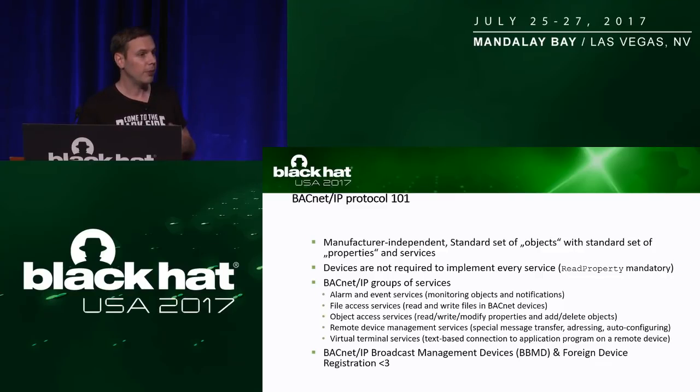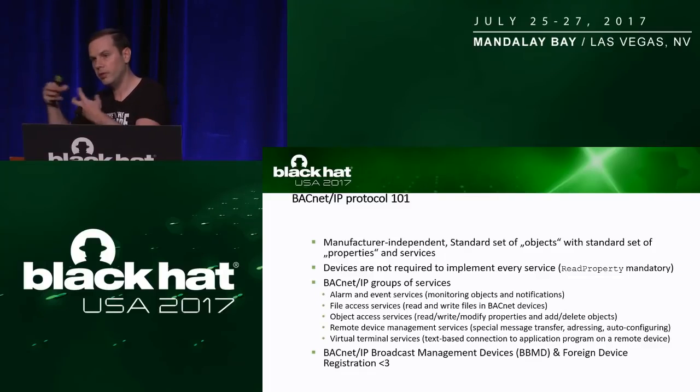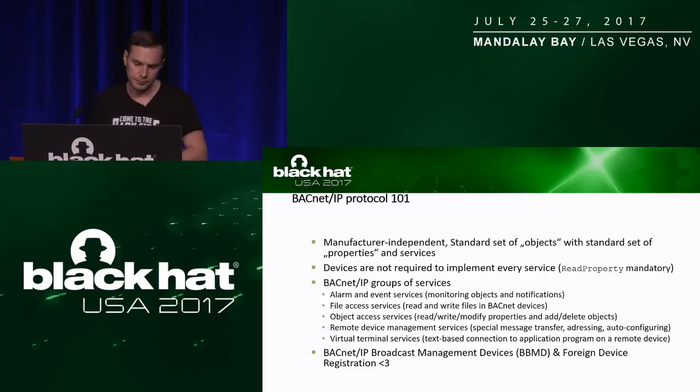And you also can see that BACnet is really a rather sophisticated protocol because it, for instance, also comes with predefined services for file access and virtual terminal services. I'm not talking about Telnet, I'm not talking about FTP, but really the BACnet counterparts within the protocol. So really, really powerful. One of the functions that we like most is the broadcast management device function, or short BBMD, which provides the capability to register as a foreign device.